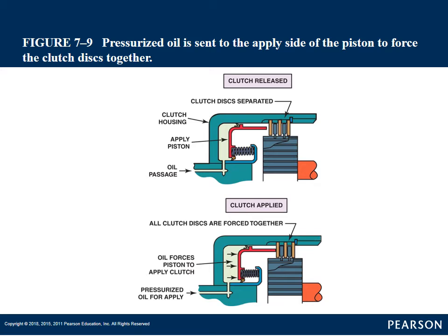That's why in older transmissions, if those lip seals get old and dry, fluid pressure is able to leak by, and the clutch pack doesn't apply, or it doesn't apply very tight, so the clutches actually slip. Instead of holding tight, the outer drum is going to want to move or slip and not hold that inner gear tight.